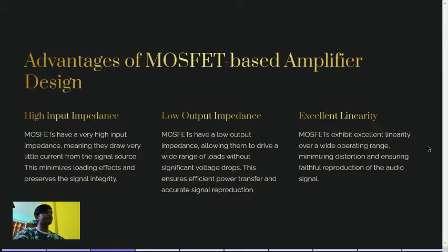Advantages of MOSFET based amplifier design. High input impedance. MOSFETs have a very high input impedance, meaning they draw very little current from the signal source. This minimizes loading effects and preserves the signal integrity. Low output impedance.